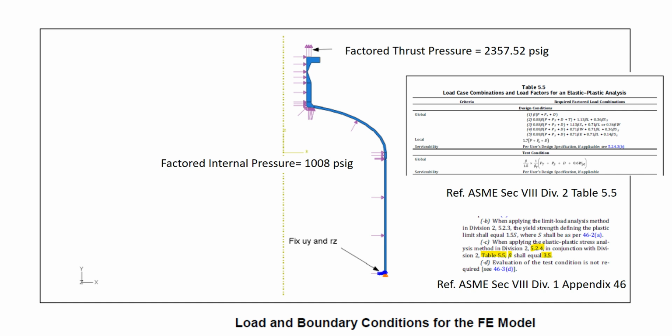So first of all, we'll understand the boundary conditions. Here you can see at the bottom, the movement in y direction is restricted, as well as the rotational motion in z direction is restricted. So we can see the coordinate system xyz at this corner.